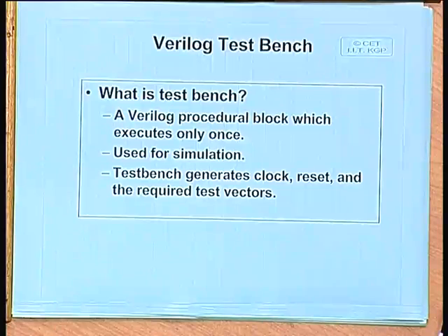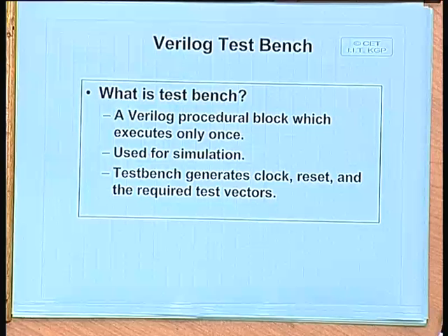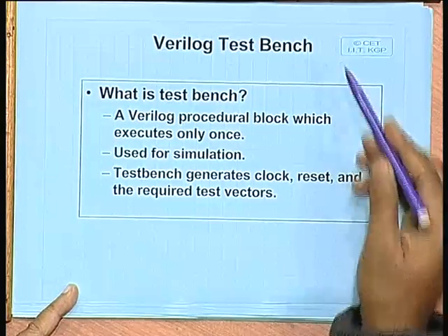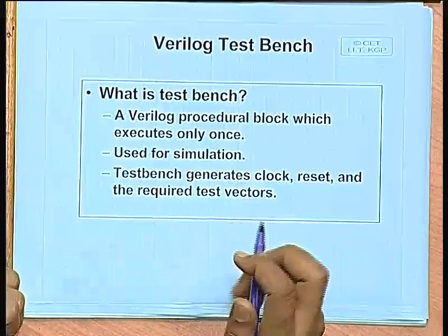But now one thing which we have been talking about, after you have written the program, you want to check it through simulation, you need to write a so called test bench. So, now let us see what a test bench really is and how it is written. See, a Verilog test bench is essentially a Verilog program.